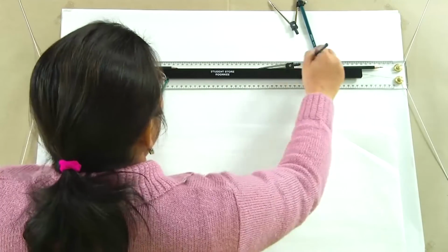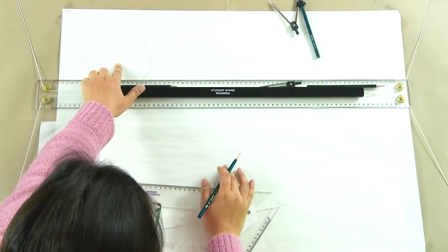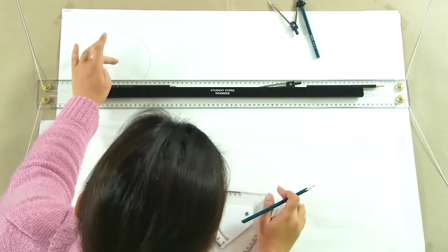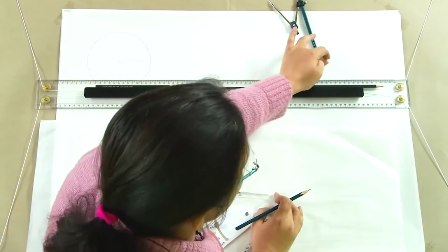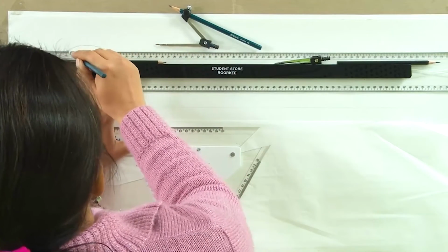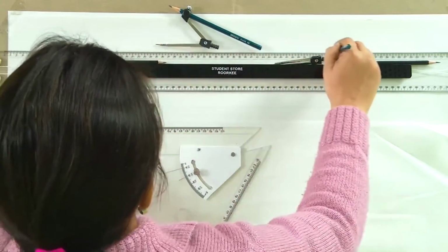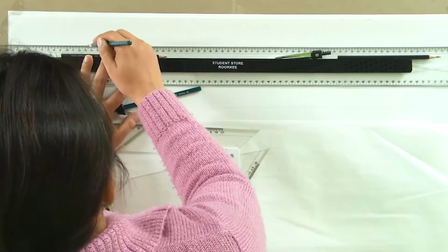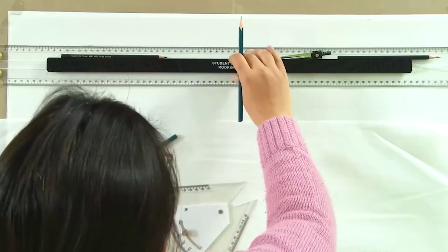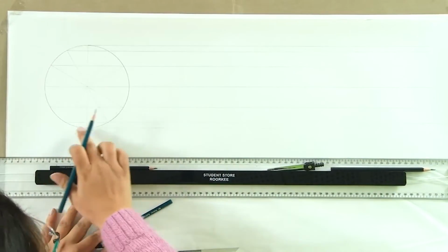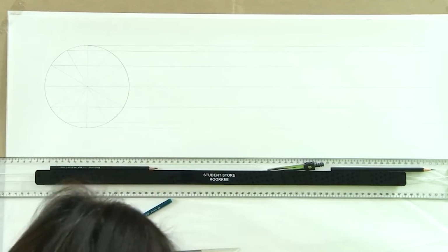This is the line which is passing through the center and also through 2 of the points. So, every time the circle rolls, the center of the circle actually remains on this line which is passing through the center. This is for cycloid. So, what we have done is we have drawn horizontal parallel lines passing through all the points which were marked by these 12 divisions.